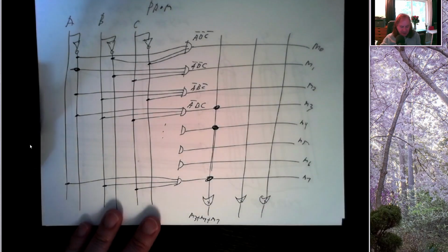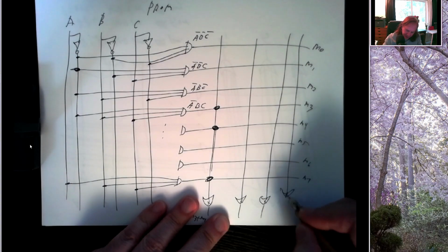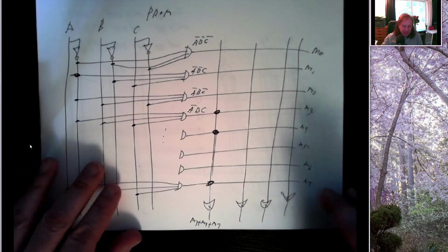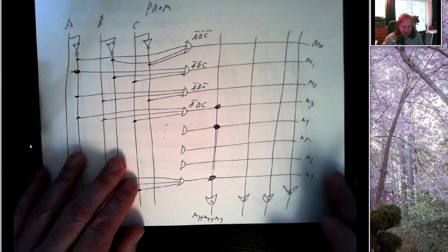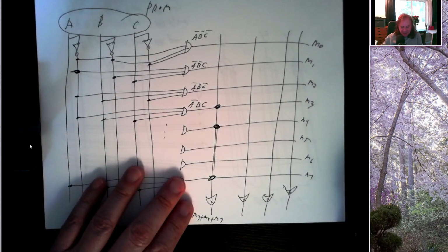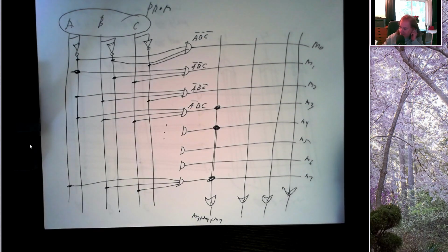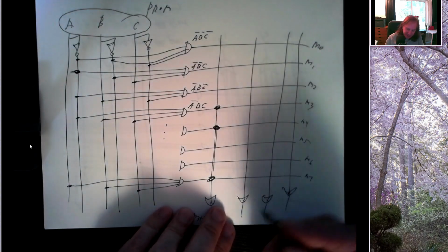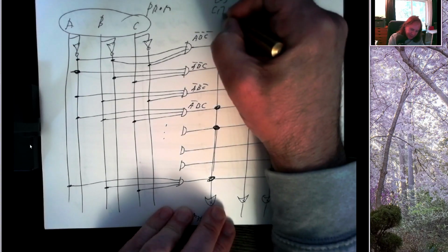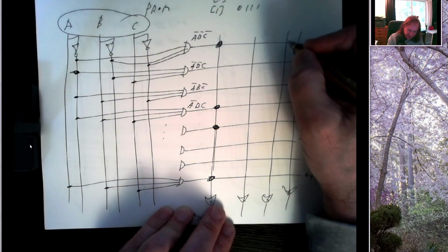And how does this work as a memory? Well, let me add one more OR gate. If I want to store 8 4-bit numbers, I can do that in this device. I can think of this as specifying an address, and at each address I can store a 0 or a 1. So for example, if I want to store at location 0 the number 1010, and at location 1 the number 0111, I would simply set my fuses like this.